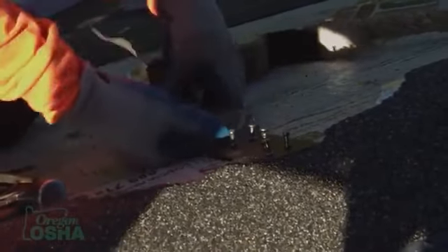So an anchor is the portion of a fall protection system that you actually use to attach to the structure or whatever you're going to use to support your weight in case you fall. Typically the type that we had used were the flat style anchors that you could nail down to the top of a roof. It basically has a nail plate with a certain number of holes, and you have to fill all of them up, depending on what type of system you're using.